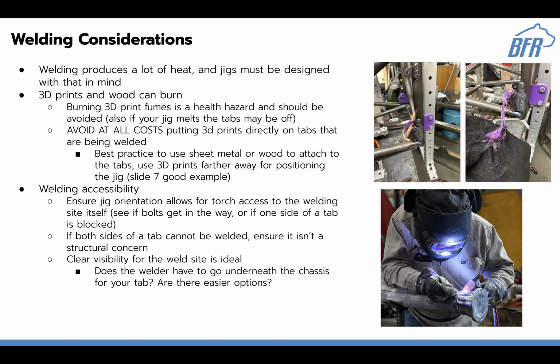The clamps will go on the chassis tubes and you'll try and space it as far away as possible without compromising the stiffness of your jig. But yeah, don't put 3D prints on tabs, please. If I see that, I'll be very sad.